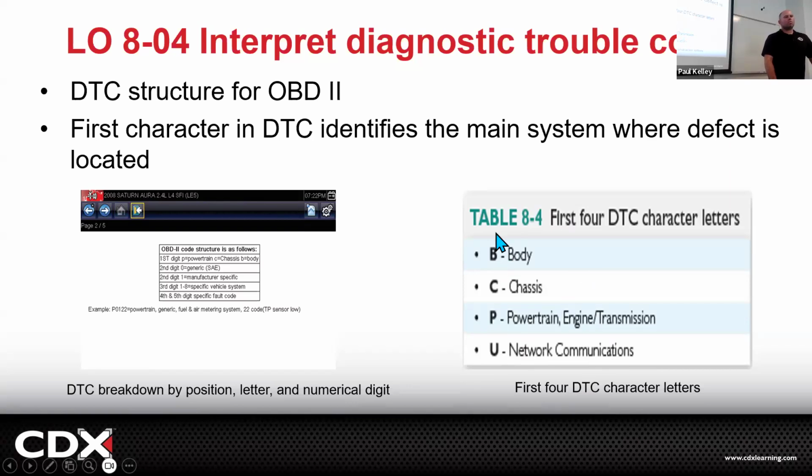I don't. We've gotten a little closer, but the problem comes down to this: if it knows it's in the circuit, it has no way to know where in the circuit. It already knows there's an issue, but for example, let's say it's a misfire. It can tell that it's not speeding the engine up, but there's no sensor to measure compression. There's no camera to look at fuel spray. There's no meter to measure the power of your spark.